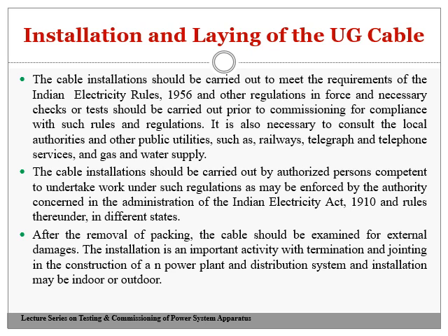Whenever we want to lay a cable, the surrounding area should be properly checked, and public utilities like telephone, water works, railways, telegraph, and gas supply should be consulted, because gas pipelines, water pipelines, or telephone lines, which nowadays are OFC cables, will be laid underground.